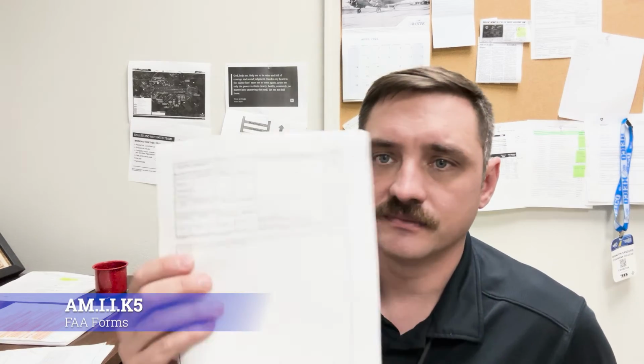Okay, so the last form we're really going to dig into is the 8010-4. Now, the 8010-4 is how the FAA aggregates maintenance information for kind of like cautionary tales, or if you remember, we studied maintenance alerts. Well, this form is how a lot of those maintenance alerts get started. If you say, like, we had this problem with this one part, it's not to an AD level type of concern, but it's something that could go wrong with it that maybe you should look at.